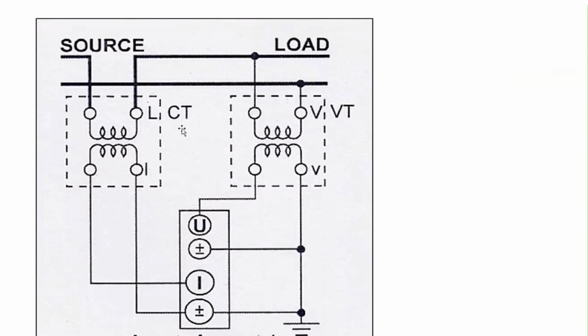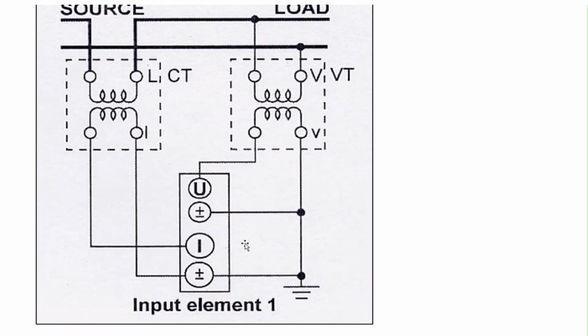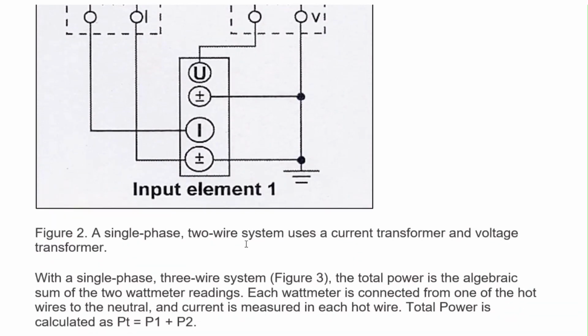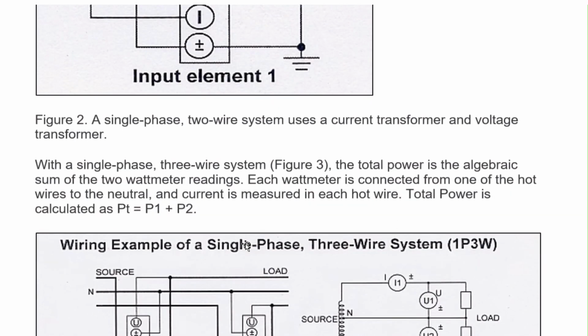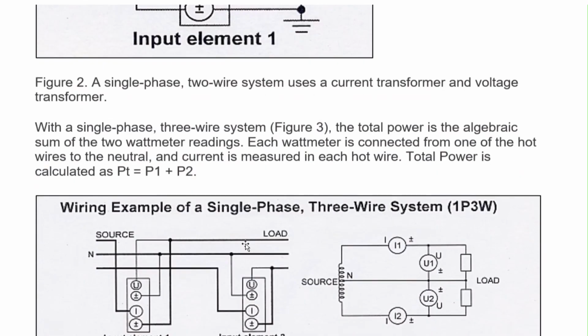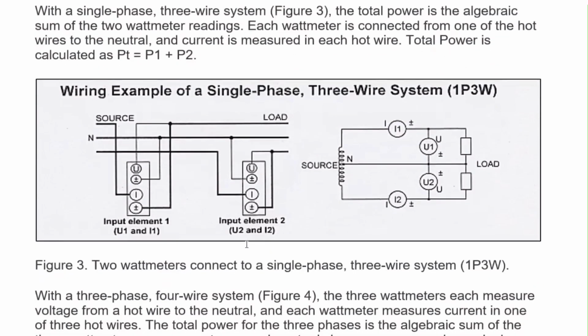There could be another situation where you need a current transformer, which is basically used for measuring a high level of current, and a high level of voltage can be measured with the help of VTs, voltage transformers. With CTs, current transformers, and by getting these two handleable levels of the voltages, you can again use them in the instruments to measure the power.